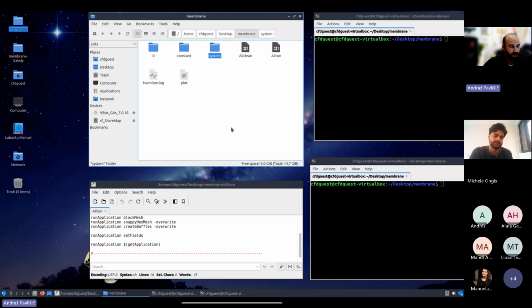If you go, as I previously showed you, into the OpenFOAM folder, you can find a lot of tutorials. In all those tutorials, you can see that you have two files, one is the clean file and one is the run file. I think they are quite obvious in what they do. If you call the Allrun subscript, all the commands are sequentially run, so that in the end you get your calculation done. And Allclean means that you go to the initial state.